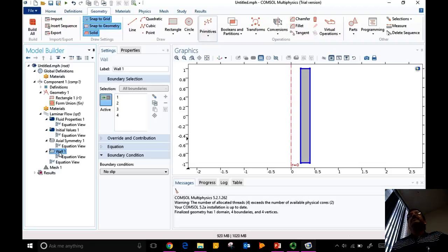It's infinite, right? So how do you simulate the infinite boundary condition is the question. Periodic boundary condition. Periodic is one. Now you need to understand the concept of periodicity, right? What does periodicity mean? What does symmetry mean? And how does it relate to the infinitely long? Because computationally we cannot do infinitely long, right? So we need to take a finite domain and mimic what would happen in an infinite domain, okay?